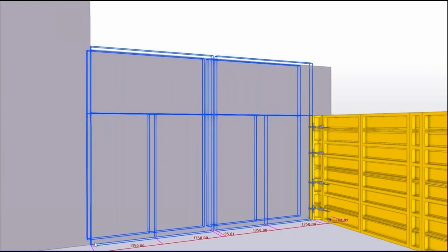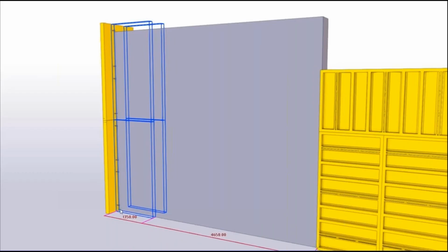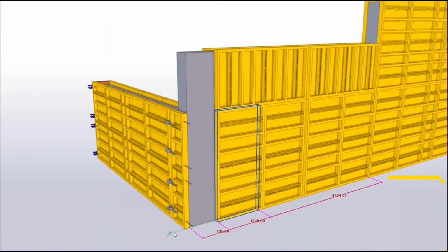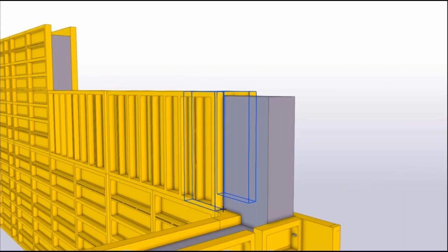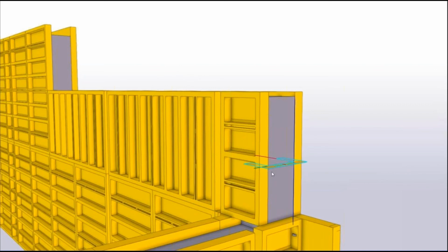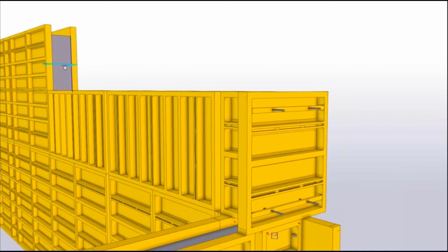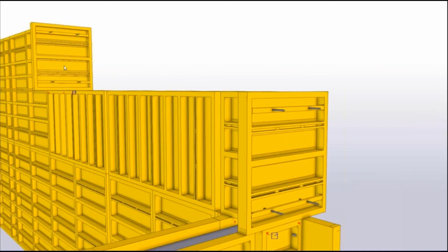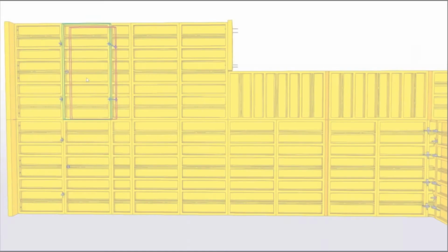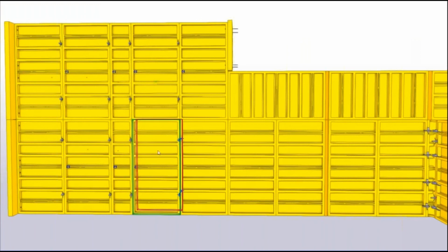And let's drag this panel here to make the corner work, and the same here at the top, and then we're ready to place those bulkhead panels at the end of the wall. And then let's start placing those fillers there between the panels. Let's close the gaps. In the new version, we now have single placing for the ties. So you get those predefined points where you can add those ties, and you can also take the ties through the filler.